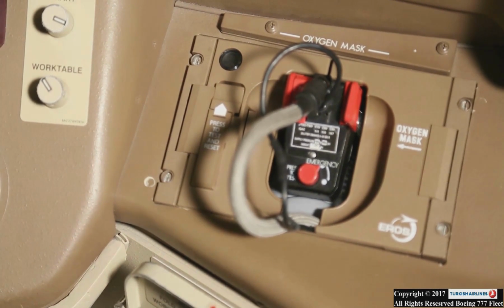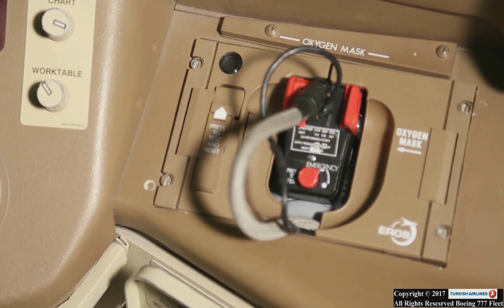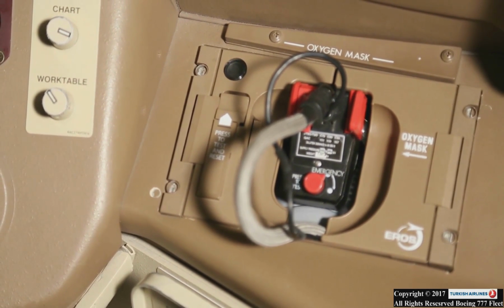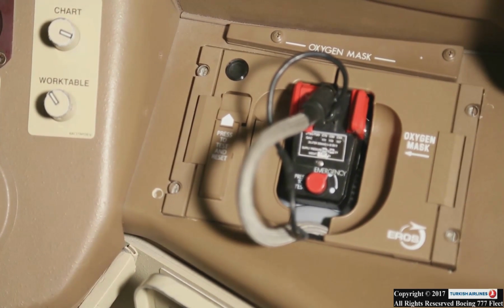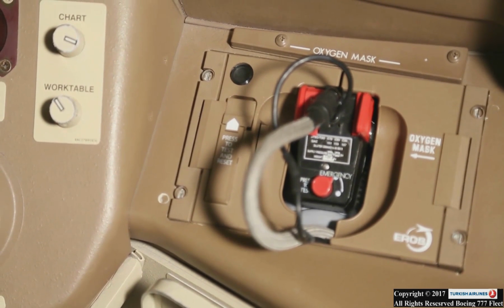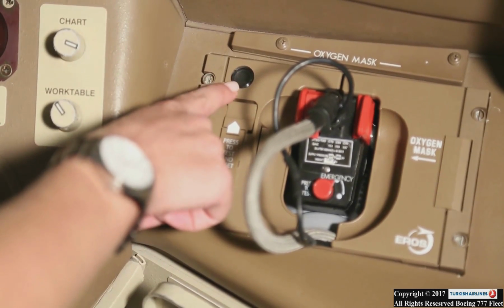If the oxygen cylinder valve is not in the full open position, pressure can decrease rapidly, decrease more than 50 psi, or increase slowly back to normal. Reset test switch and the emergency test selector, release. Verify the yellow cross does not show in the flow indicator.